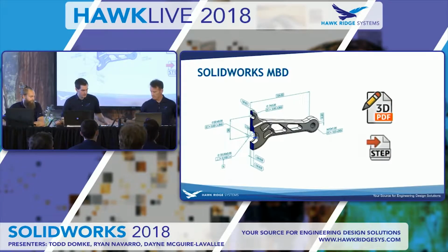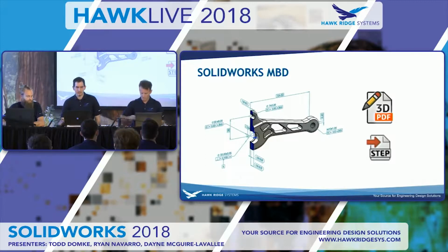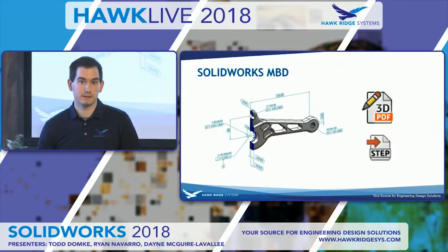So yeah, the first thing I want to talk about here in terms of documentation is SOLIDWORKS MBD. And MBD is really a new initiative in the industry, stemming from aerospace and defense industries, for the idea of defining all your product manufacturing information, or your dimensions and tolerances, which we sometimes shorten as PMI, strictly on the CAD file rather than making a 2D drawing at all.